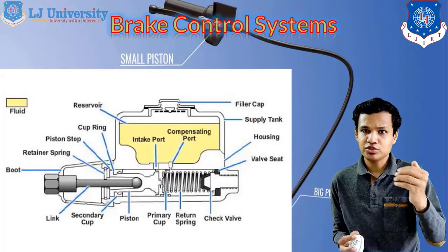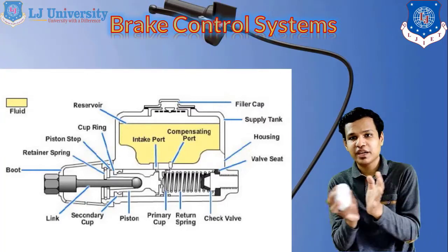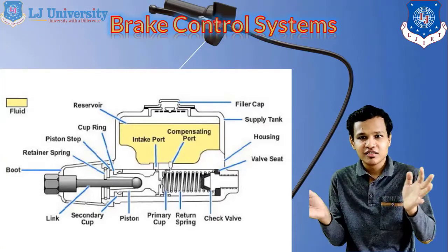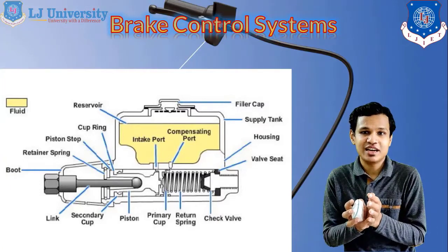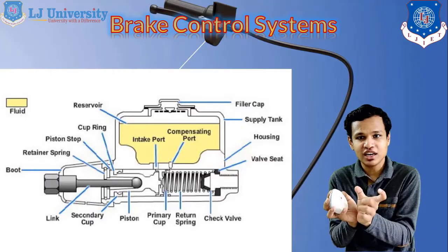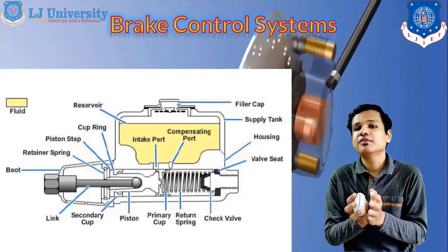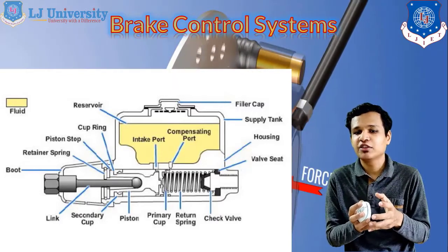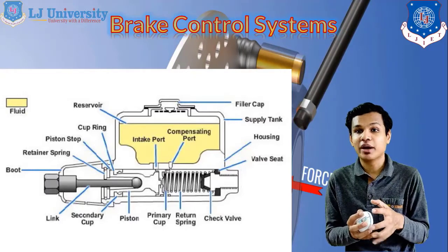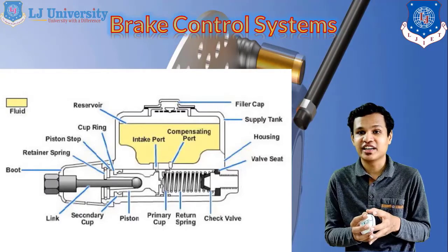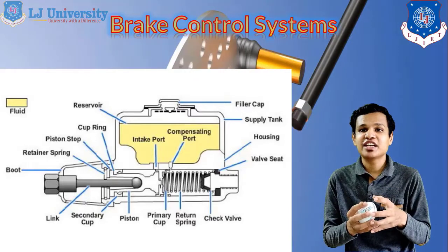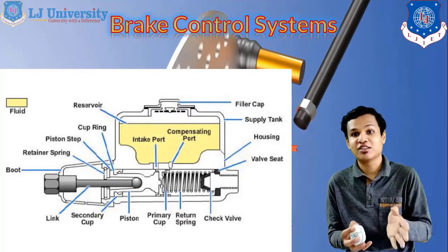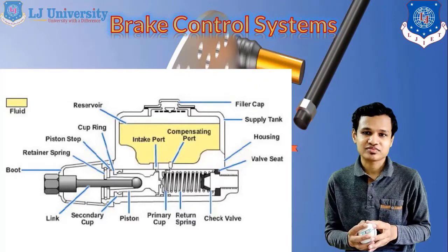When we push the piston, the spring will compress. Also, the oil which is filled in that space will be pressurized. Because the piston is going inside, the volume between them decreases and the fluid pressurizes. Because of that, high pressure is created in the oil and the check valve will open. That pressurized oil is further transmitted to our brake lines, which are connected to the check valve.